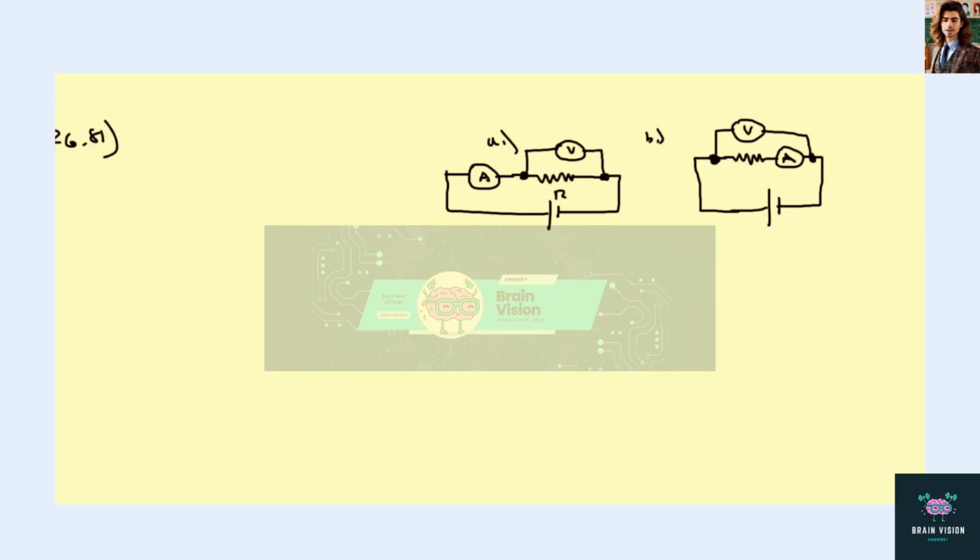If V is the voltmeter reading and I is the ammeter reading, the value of R will not quite be V over I, as Ohm's law states, because some of the current actually goes through the voltmeter, so that the actual value of R is given by that expression. And it says, note that it approaches V over I for Ohm's law if the voltmeter resistance is really great.